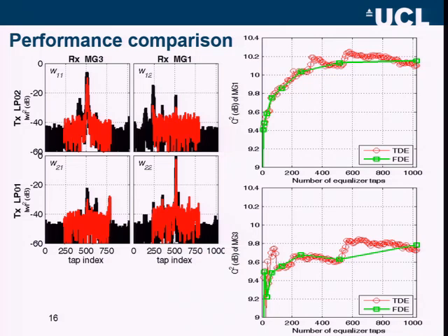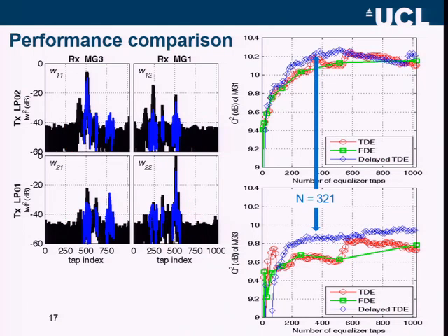So in order to get rid of this additive noise between the impulses, we can actually use a delayed time domain equalizer. Here we show the improvement of the system performance, and we can also see that at the very beginning, all the channel impulses has been covered, so all the jumps in the Q-factor curve has been removed. It still suffers the same issues when you keep increasing the number of taps. It will include the noise that are from the inactive taps.